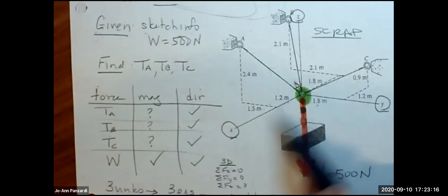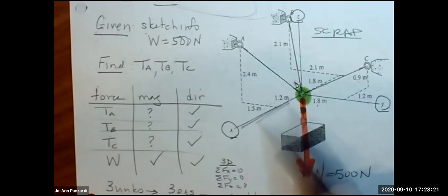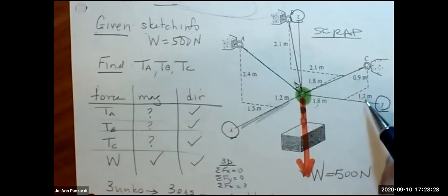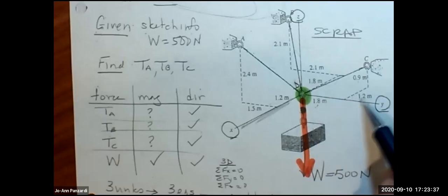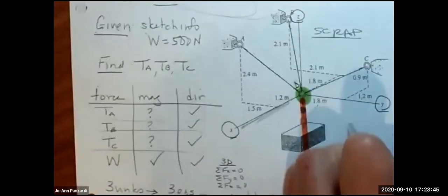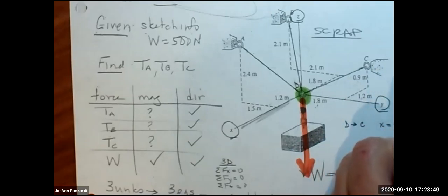Here is the X-axis. It means that the distance that's parallel to the X is the one that's the X distance. So Daniel, is 1.8, 1.2, or 0.9 parallel to the X-axis? 1.2 is parallel. So going from D to C in the X is 1.2. And is it positive or negative? It would be negative. So going from D to C in the X, it's negative 1.2.